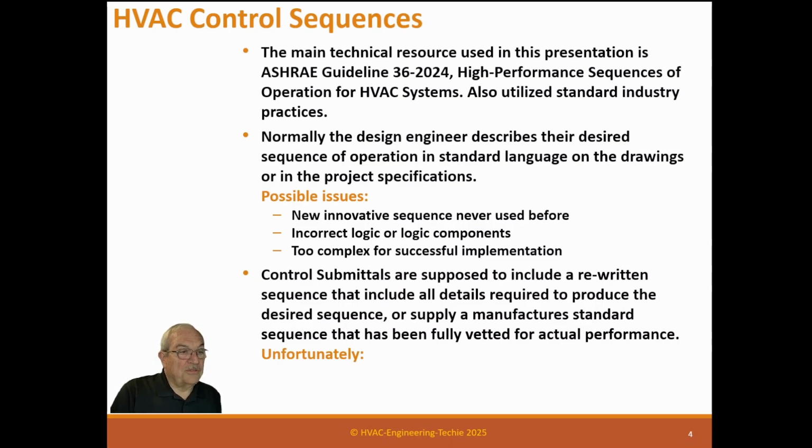There's a lot of entrance and exit points. There's timers. There's certain things that happen. There's resets. There's all kinds of things that need to go in there that I, as a commissioner, need to know to actually test it. If I don't know that, then I have to guess at what we're testing. And many times, doing that, you actually write a test that can't be successful because you didn't understand that the guy had a part in the sequence that actually affected what you're trying to test. So we need to be plain and expose what the actual sequence is going to be.